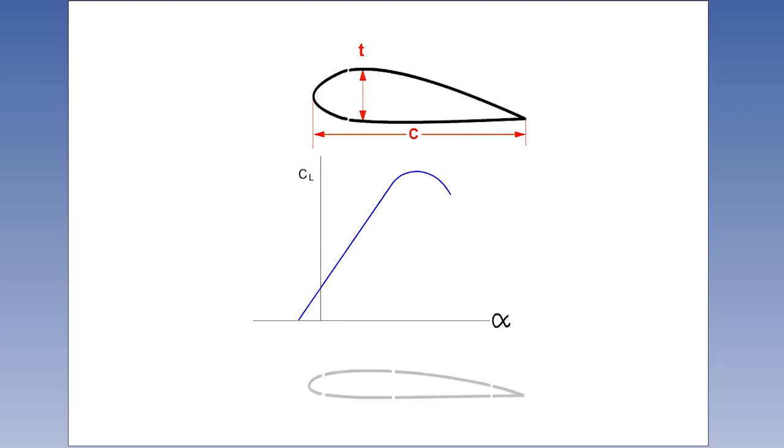These opposite features are more typical of a wing designed for efficient high-speed operation, with a sharper leading edge, a low thickness chord ratio, and an aft maximum thickness and camber. A comparison of the shapes of the two lift curves shows the difference between the profile's stalling characteristics.